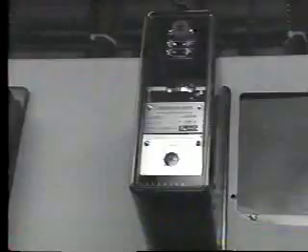In the last segment, we pointed out that the normal differential protection scheme will protect for ground faults, as well as phase-to-phase faults. This is because the relay is sensitive to the unbalance caused by the ground fault, as distinct from direct measurement of ground fault current. However, in some cases, a ground differential relay, 87GD, is connected to measure and operate on zero-sequence ground fault current.